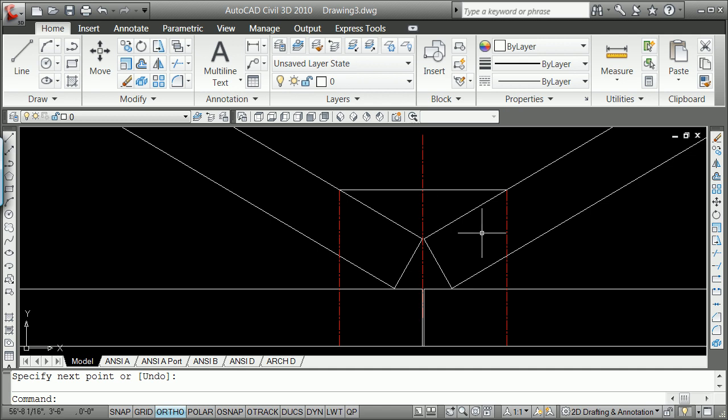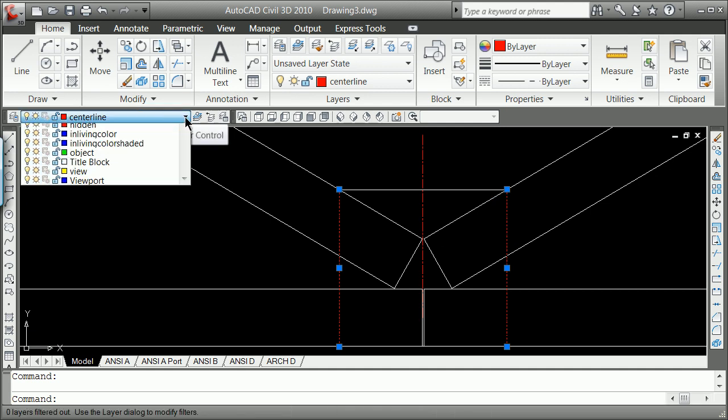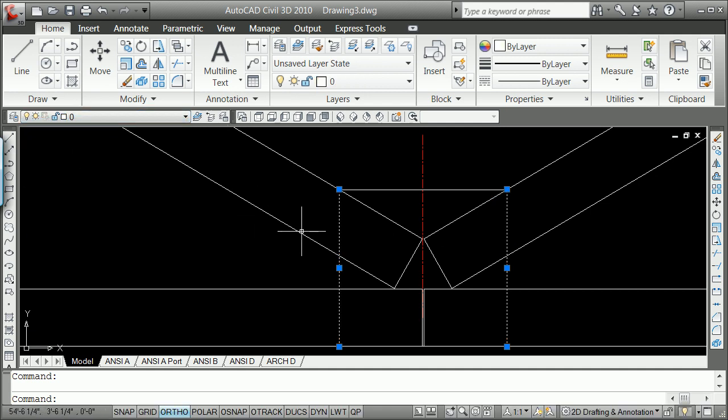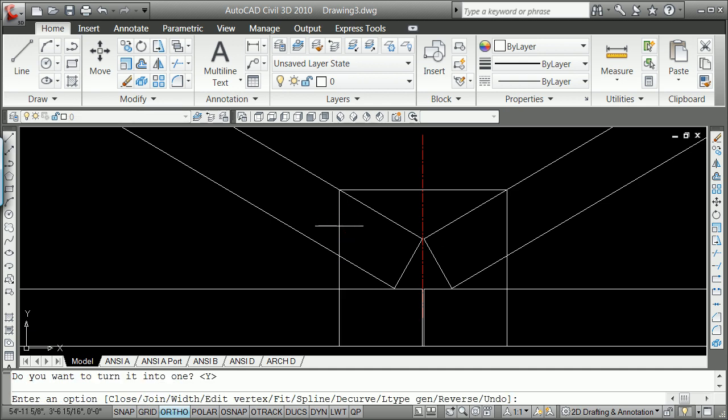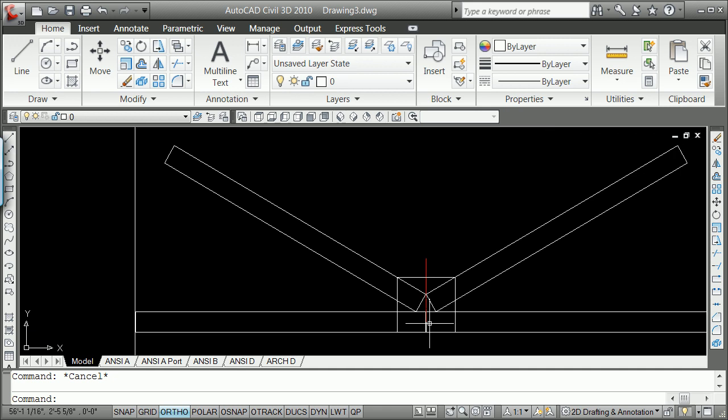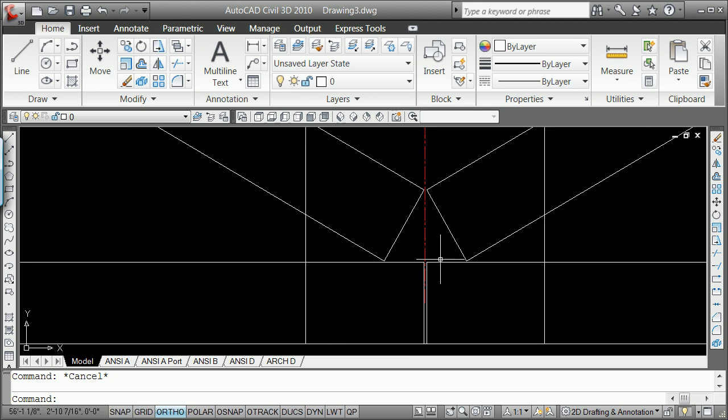So I'm going to finish out this gusset plate now by changing these two things to the correct layer, which for now we're calling layer 0, and then doing a PEDIT. Grab that one, yes, J for join, 1, 2, 3, and then finally saying close, as we're apt to do. And now we have 1 piece, 2 pieces, 3 pieces, and I'm just going to do write blocks out on 3 of the pieces.